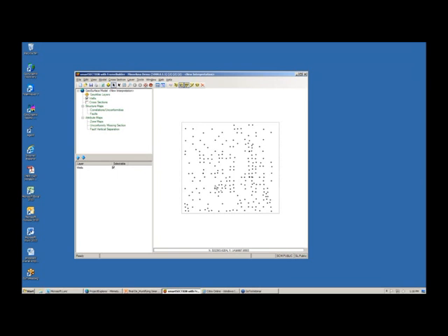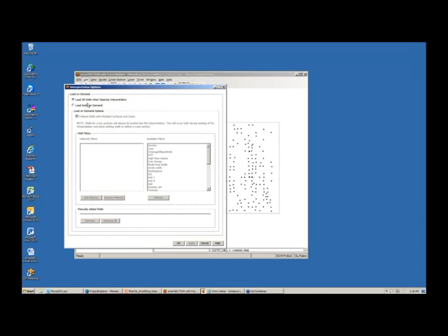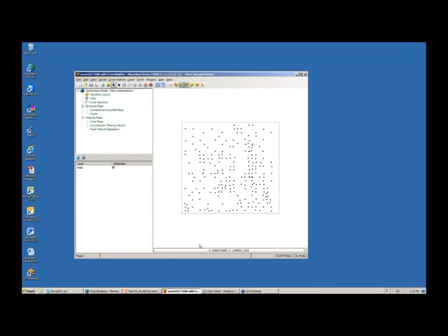These filters are very easily created or may already exist, since all filters previously made by you in GeoAtlas and WellBase are automatically available. To see the filters that are available, you'll just go up to Edit, Interpretation Options, and you would see a list of all the filters that you've ever made.